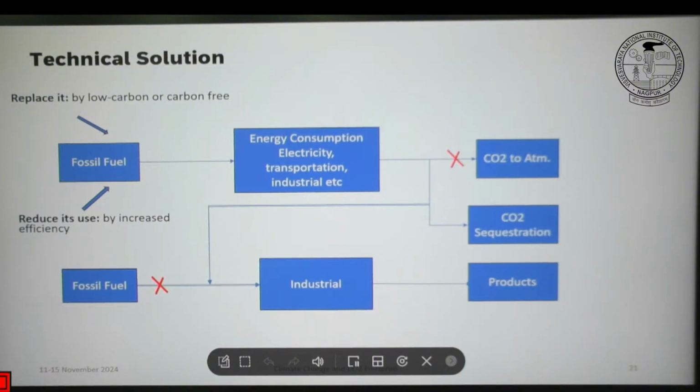Nowadays CO2 is also used industrially as refrigerant, replacing ammonia because of safety. So although the GWP is higher for CO2, it's a greenhouse gas, but as a refrigerant it is much better than ammonia. So traditionally we always had ammonia as refrigerant used in industry, but because of the safety aspects and other issues, CO2 is replacing ammonia.